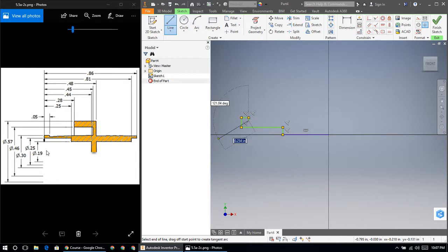And then this is at an angle, a diagonal. That diagonal comes up here to the right. Notice I want to get away from where it snaps to these two endpoints. I'm going to control this, so I'm going to move it up here a little further and further out. I'll come back and clean that up with dimensions in a little bit.